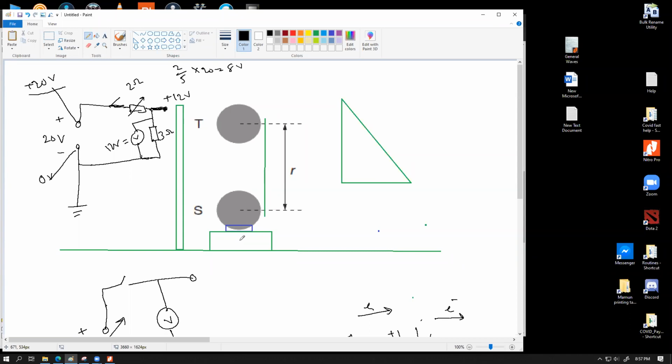What we can do, we can now press that tare button. Every top end balance has a tare button. Tare basically means it's a sort of a reset. If you press that, then the top end balance will give you 0. It means it will read all the weight or mass on top of it as a balanced load. It will measure all the load above that. That's one way to do this thing. You can press the tare. That way, whenever there will be a force variation, this will read that force variation.